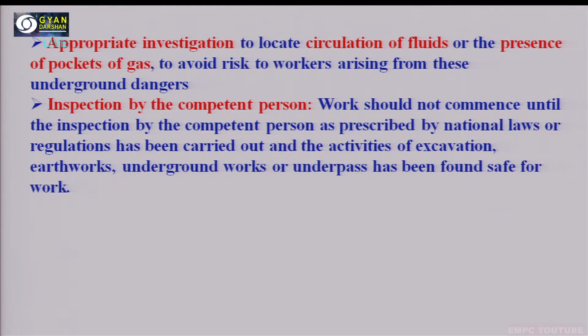Next is that before starting our work, proper investigation of the site has to be done. What are the risks associated with that particular site? What type of material is there, whether loose material or loose earth is there? So we have to make proper arrangements. Whether some gas is present there, whether land contamination is there, whether some gas pockets are there. So we have to make proper investigation before actually starting the work. If we do that, we can avoid any accident.